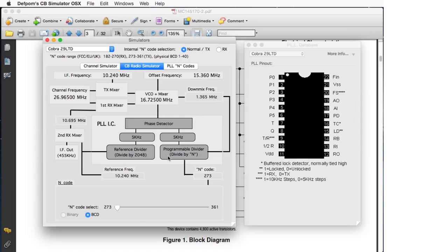But the issue with PLL theory is that if something isn't working correctly, you don't know where to start. Right? Well, not easily. It may not be obvious where to start, because it's a loop. If something's wrong with this frequency, this won't work right. This will be trying to correct for it and sticking either a full 5 volt out or 8 volt out or nothing.